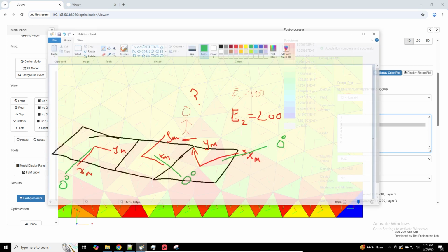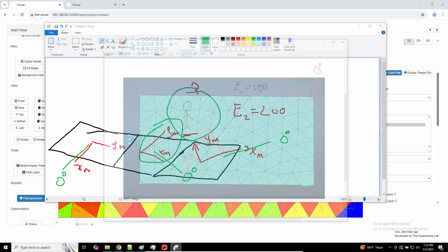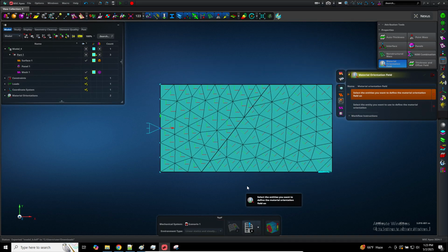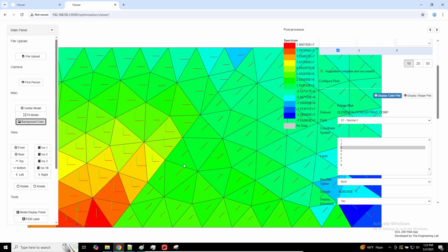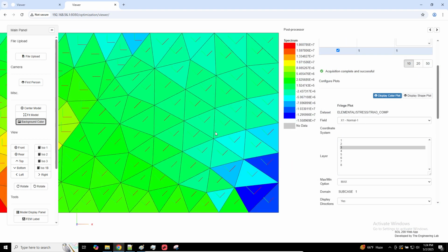We realized that, hey, my material coordinate systems were never modified. They were left to point in completely different directions. So then what we did is we went in Apex. We said, you know what? Take all the material coordinate systems and make them parallel to these different local coordinate systems. And this is the result. The sigma 1 stresses for this side are all pointing in the same direction. And then the sigma 1 stresses for the other side are pointing in this direction.